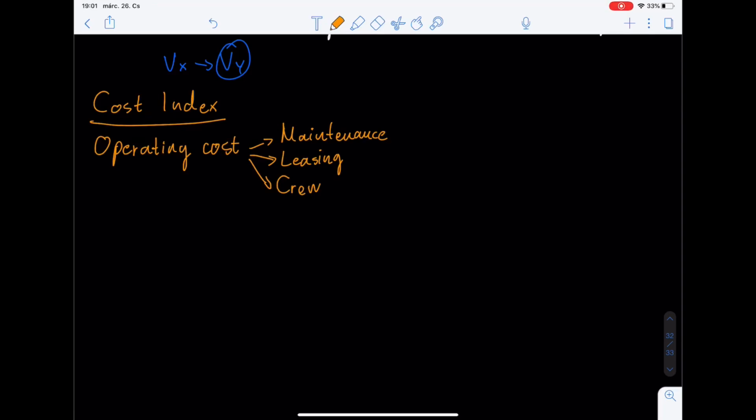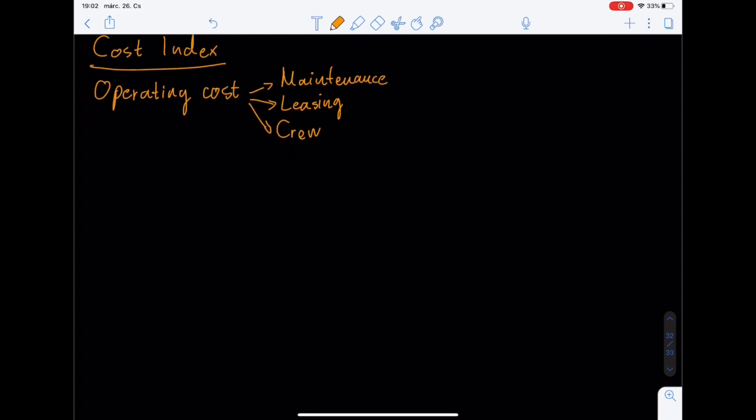And here's where you have the definition of the cost index. The cost index is basically the ratio of the time-related cost of an airplane operation and the cost of fuel. So the value of the CI reflects the relative effects of fuel costs and overall trip costs as compared to time-related direct operating costs. So in an equation,